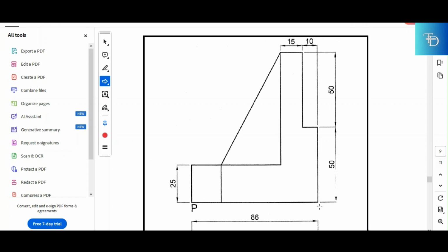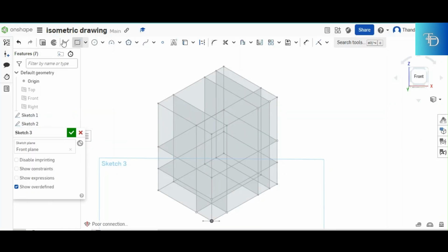You go back to your question and confirm which lines you can outline, starting with the front side. Right there at the back, you have that huge step that is 50 millimeters. You go back to your drawing and you mark that 50 millimeters from this point to that point right there. And then it goes in by 10, and then it goes up to the end, and then it goes in by 15. Now you're just outlining the whole drawing. It's within the cube. So now we are just outlining what you can see, because now you know you have this. Then the next thing you know that you have that closing there.